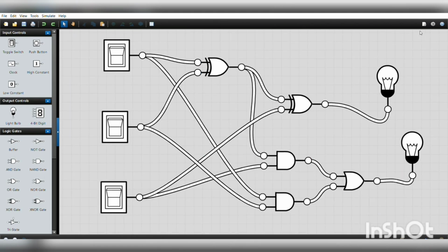I have designed all these circuits based on the circuit diagram, and let us see how the input and output operation works. So moving on to the full adder circuit, a full adder circuit generally consists of the XOR gate, AND gate and OR gate. So the sum equation is given by A exclusive-OR B exclusive-OR C and our carry equation is given by A plus B into C plus AB. So this is our sum output and this is our carry output.